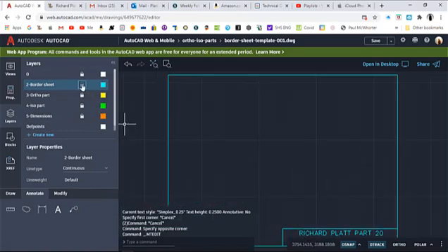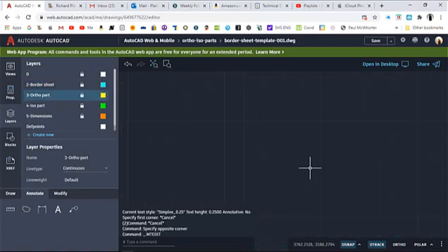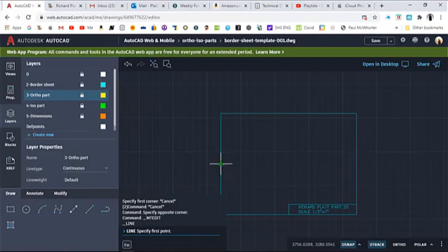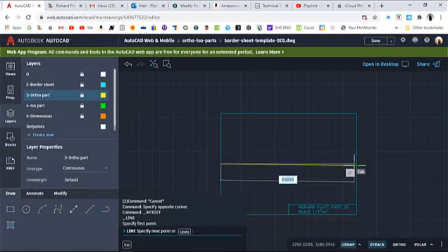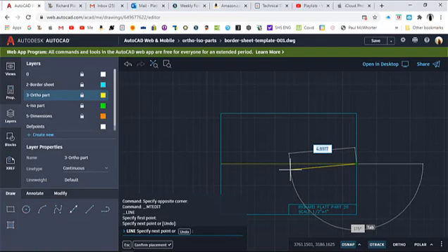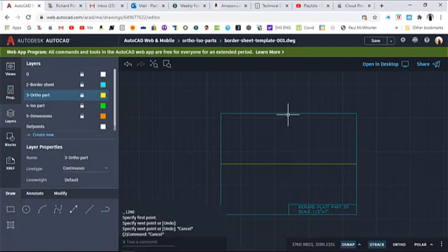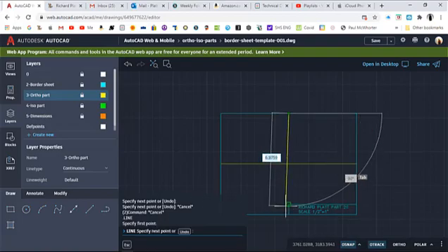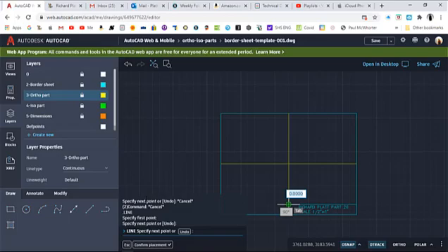And what I'm going to do now is lock that layer and go ahead and get on to the Ortho Parts. And we're going to draw this very similar to how we did it last time. So we just zoom out here. And I'm going to go get my line command. And I'll just come over here and find the midpoint, because it should still have all the same object snaps put together. I hit the escape button, come up here to the midpoint on this, go back to hit my space bar to go ahead and relaunch the draw line command. And that looks pretty good.